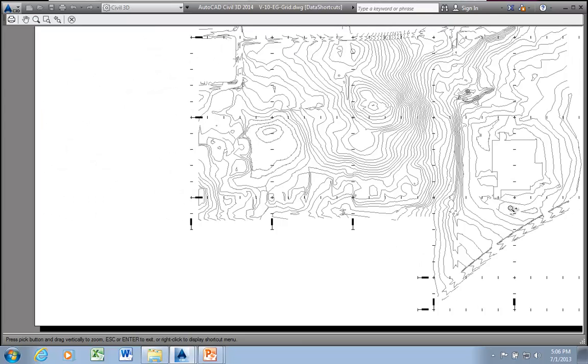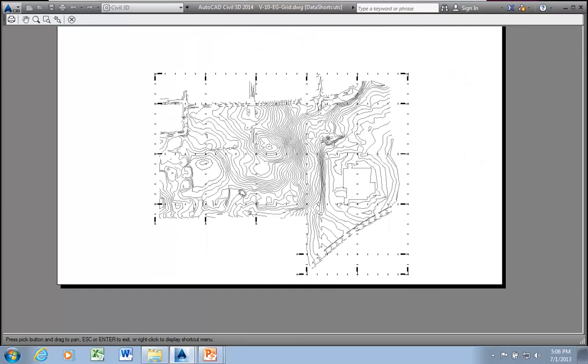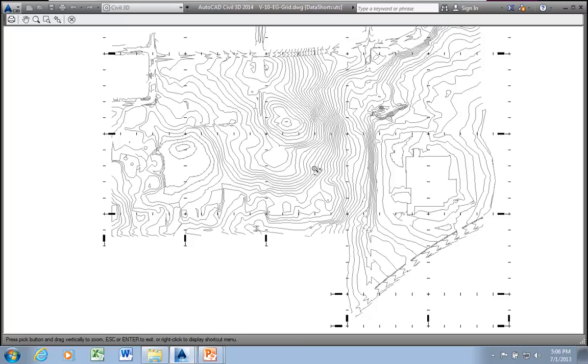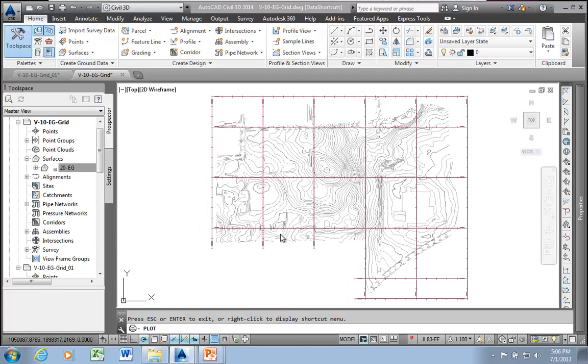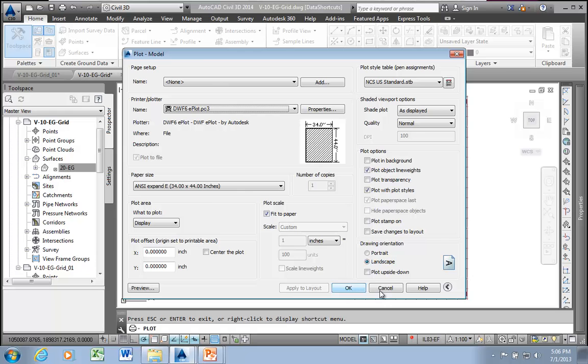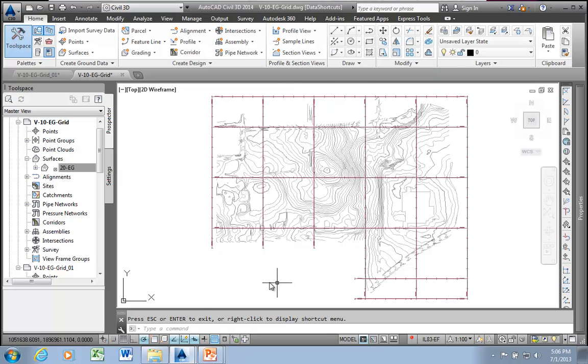I would do that before I applied and built all the offset alignments. Typically make that decision beforehand. It's a lot easier. The other choice is simply get rid of all the offset alignments and rebuild them. They're easy and quick enough to build. Nothing difficult about building a grid out of alignments in Civil 3D.